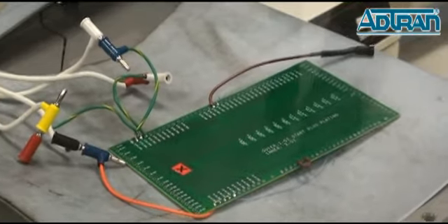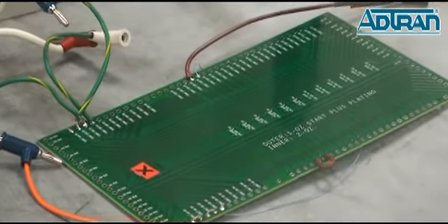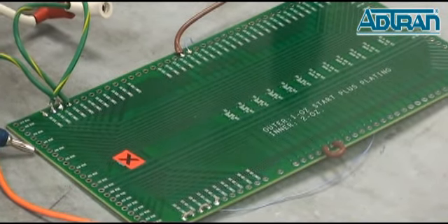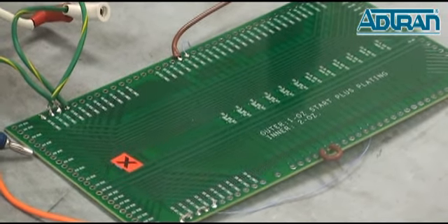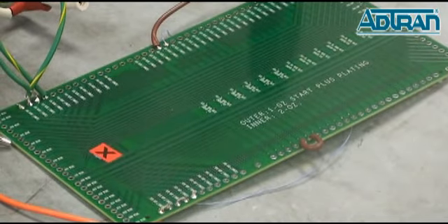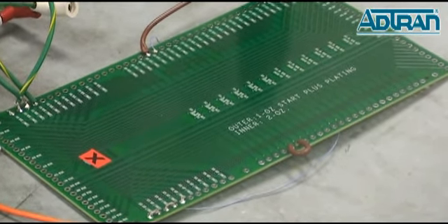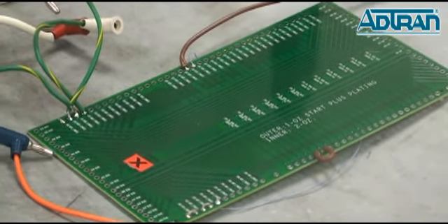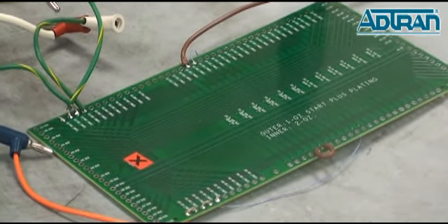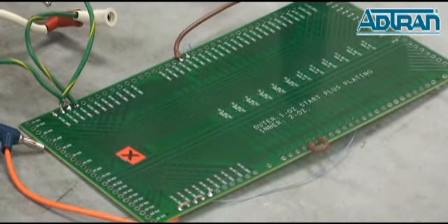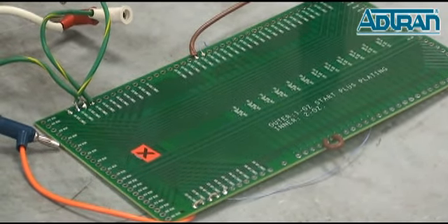Okay, should be fun. What we're going to simulate here is an AC power fault condition where AC power lines came in contact with the tip and ring wires coming in from the telephone interface, and we will be running about 30 amps through this circuit. Our circuit cards could see this kind of a fault in the field, so this is one of the things we want to evaluate for. And what's happening right now? Right now the machine is starting up and getting ready to drop the voltage and currents onto the wires going into the circuit board. The voltage is building up to 300 volts and he's ready to run.